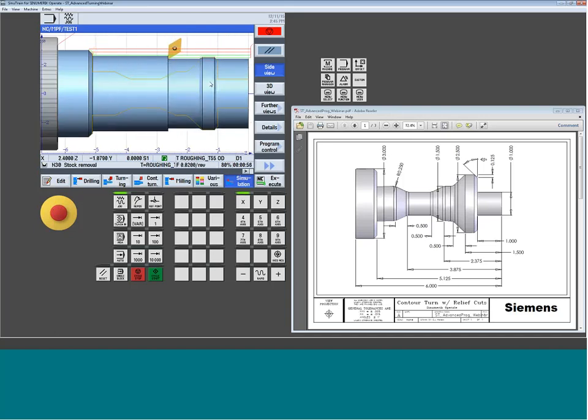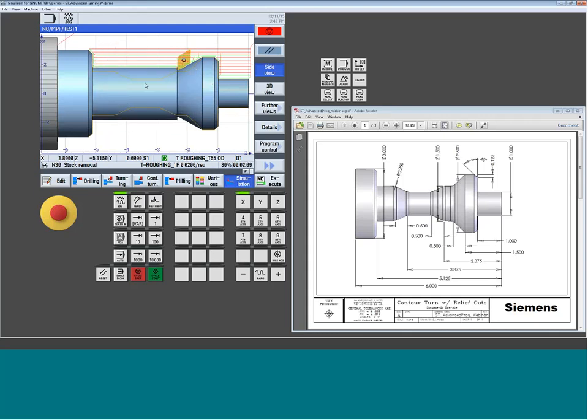So I come in, it starts machining, and you can notice now with the back side of that tool, once we get there, it's going to get me a lot closer to the orange line, which is the finished geometry that I'm trying to get to. So this would probably be a viable, a little more accurate scenario for machining this part out. But I do now have to handle this material, and that's where things could get a little trickier.